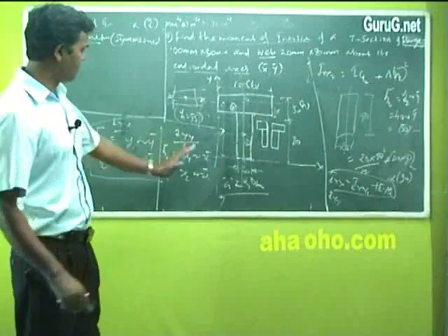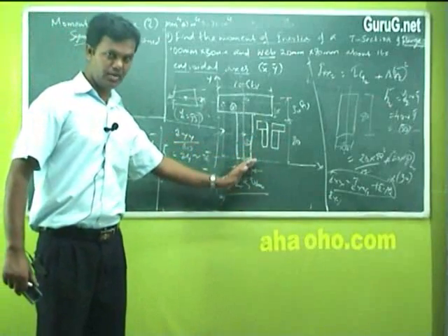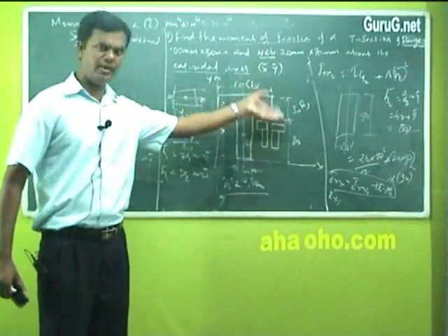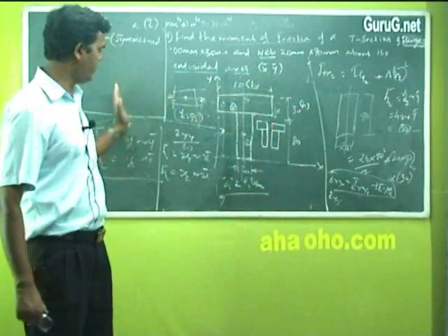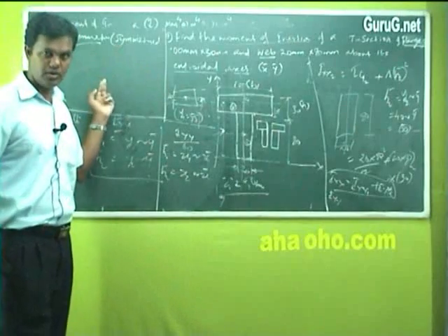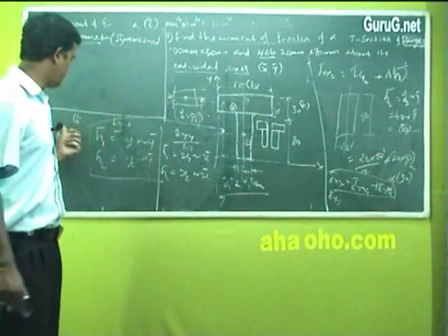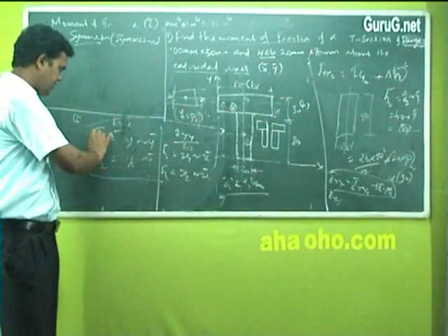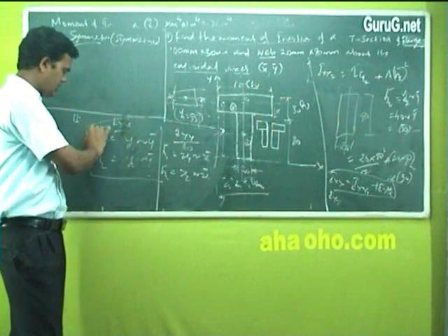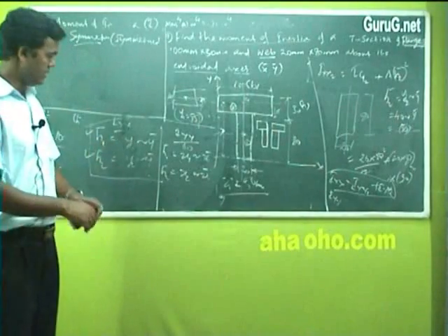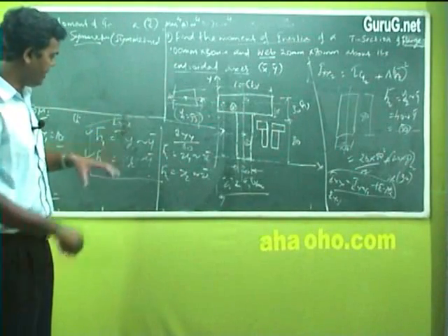So after this step, finding x bar and y bar, right? Y bar you solve by A1 y1, A2 y2 and find the answer. Then you go for your moment of inertia, using those formulas. The only difference is that a different approach is required to find out h1 and h2, the h bar, to find out Ixx.